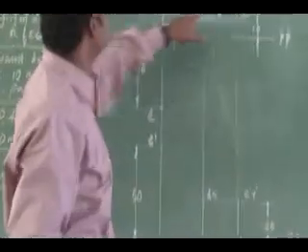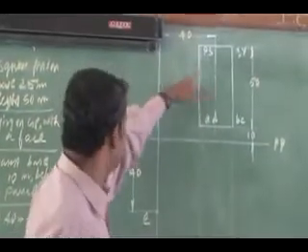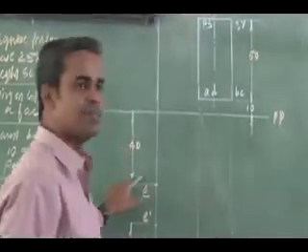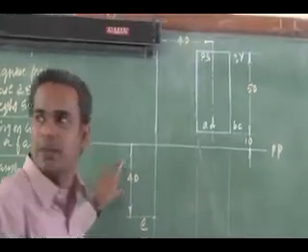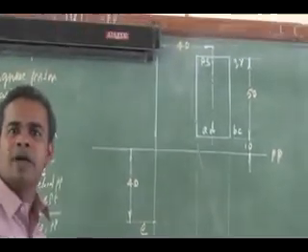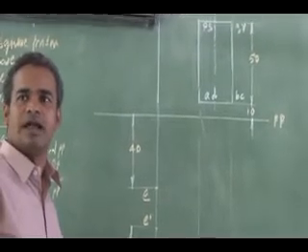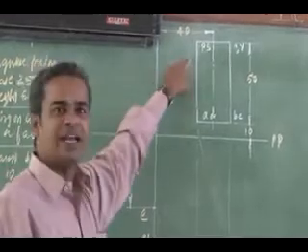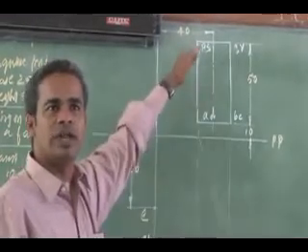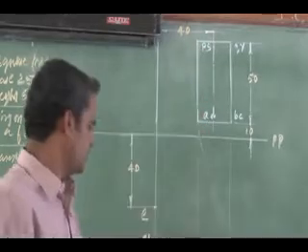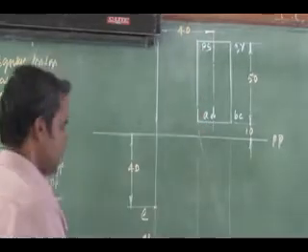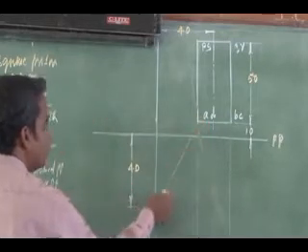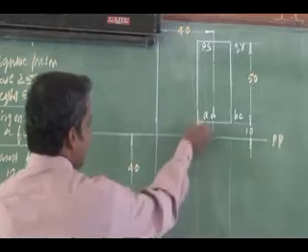The remaining thing, the center plane: the station point is 40 mm to the left from the axis of the solid, and the station point is 40 mm in front of the picture plane. At the same time it is 50 mm above the ground plane. So I have marked the station point, front view and top view. This is the layout. Then you try to get the intercept of all the corners and get the perspective view. By joining the corners to the station point in the top view, I can get the intercepts as usual.